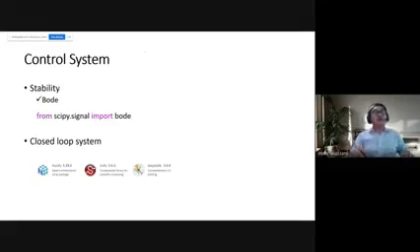All right. And then for control systems, before we design a controller, we need to check the stability. We have many ways to do this. You can use root locus, we can use frequency response with Bode, or in the s domain we can use the Routh array, all those things.